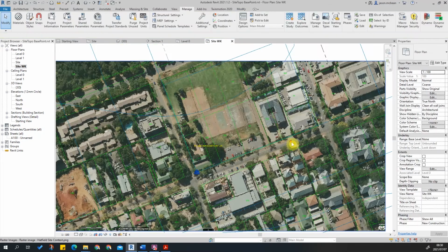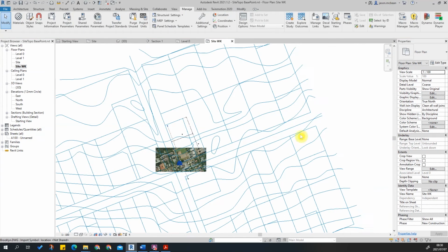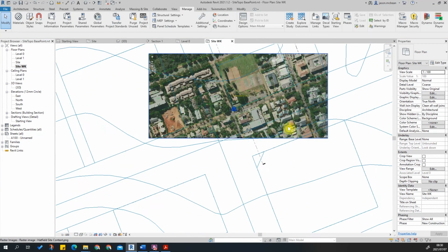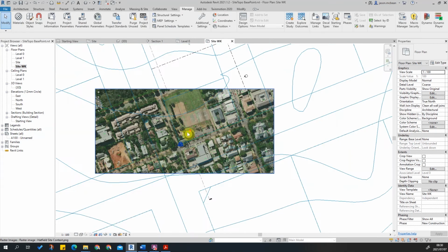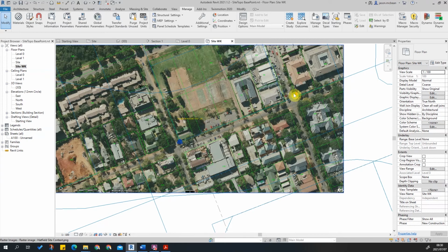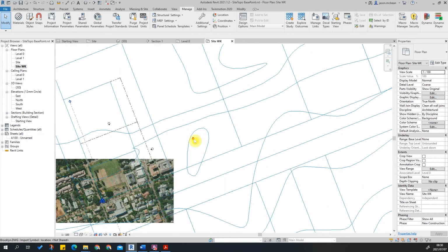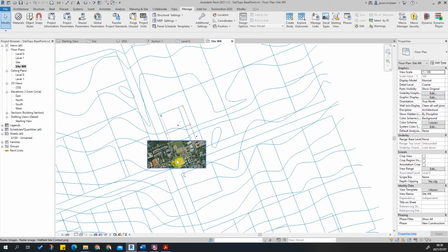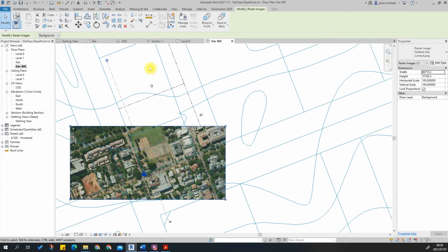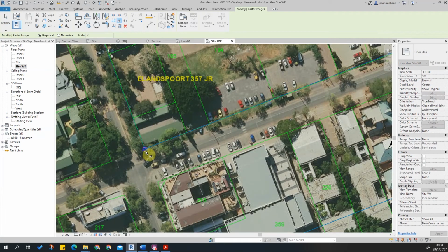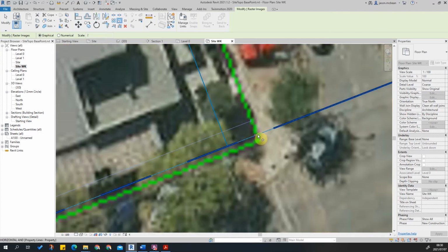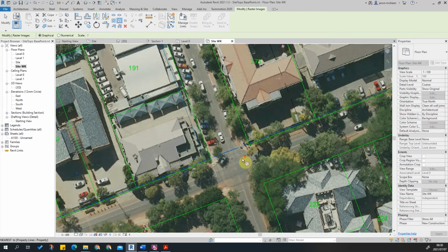The last thing we need to do is just use the scale command. I've got cadastral information in all directions. So in this instance, I can clearly see how this works. I'm going to try and scale, I think, the road markers over here. So we've got these two narrow sites, 1, 2, and then we've got these two little block sites at the end here, and you can see where they are. So I'm going to use this to scale. Grab my image, use the scale command, select my origin, and then scale from here, and that's going to go right to the end.